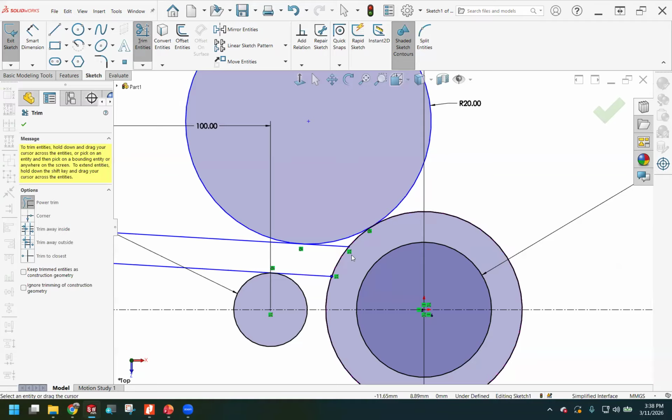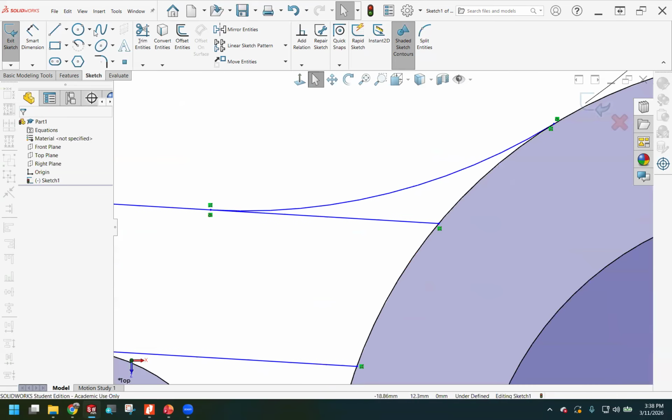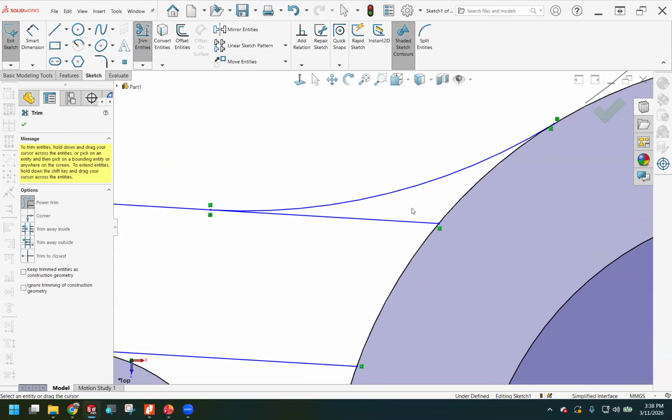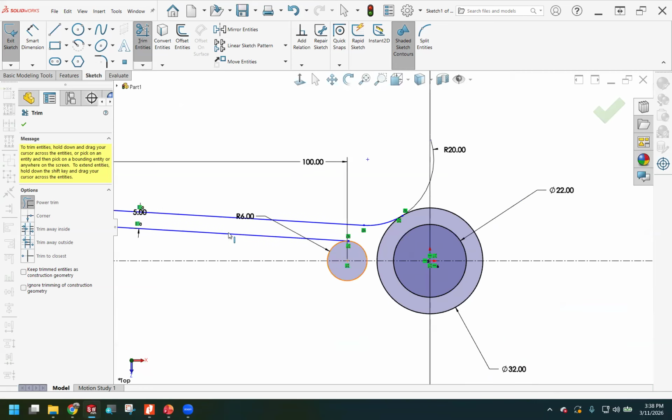And the reason why I'm doing this, creating a second circle up above it instead of creating a fillet, is I want to preserve this contour here whenever we do the next step. So I now have a nice little arc connecting tangent to this circle and tangent to this line. And I can go in and trim off this end and also this end for that matter.